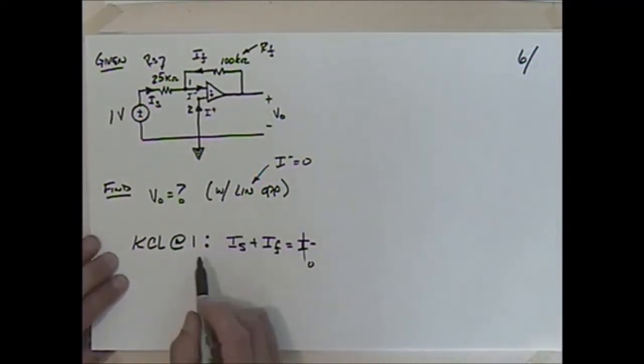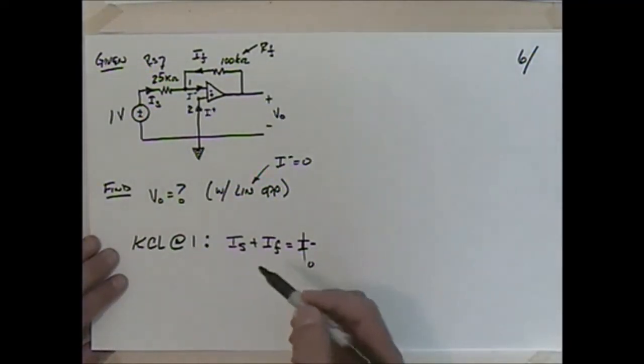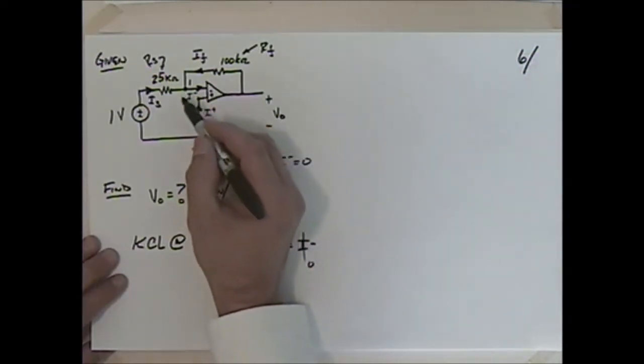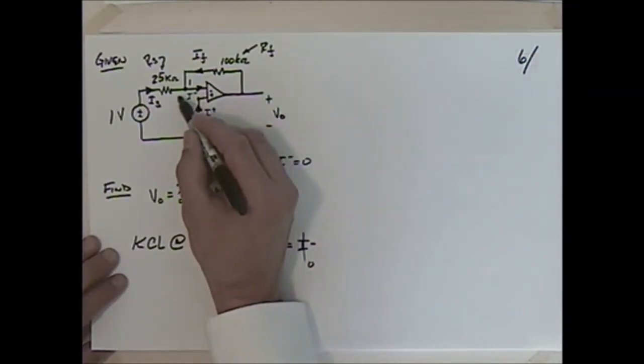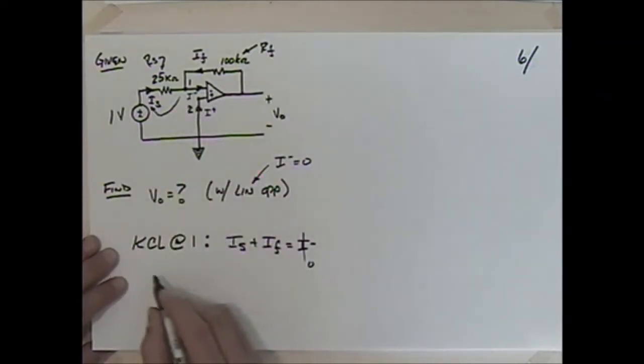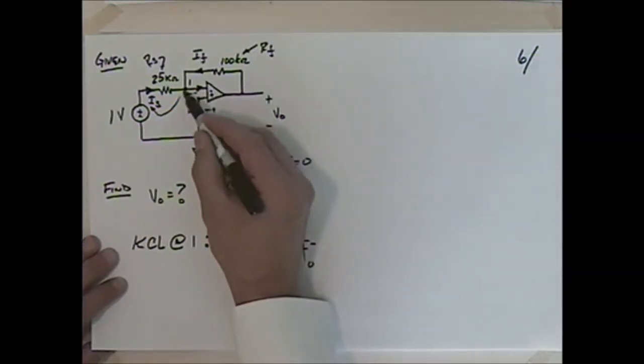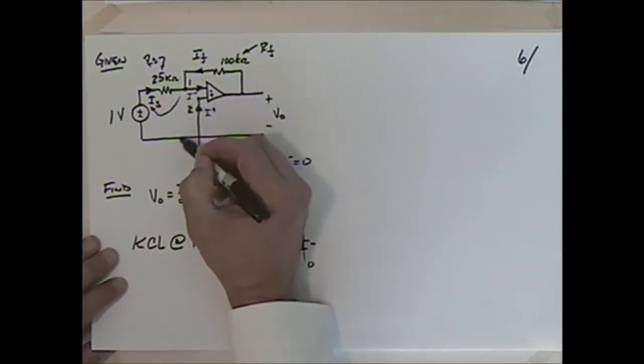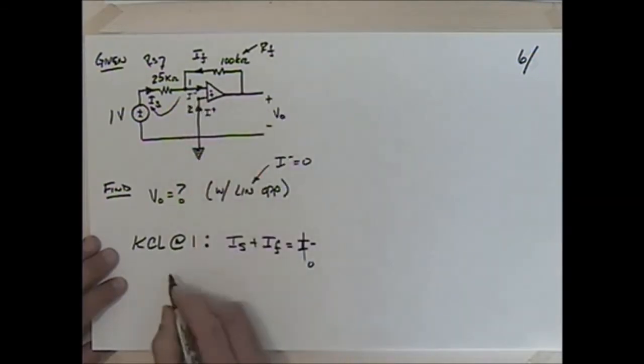So now let me talk about IS, and this is where you need a good command of node analysis, because you almost always do this with node analysis. If I come in here, I've got the current going to the right, so I need to find the voltage potential going that way, don't I? So IS is really equal to getting from 1 back down to the ground state, so that'd be minus V1, right?